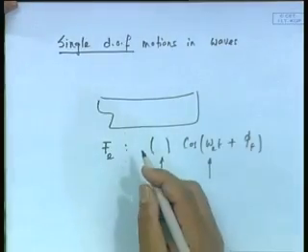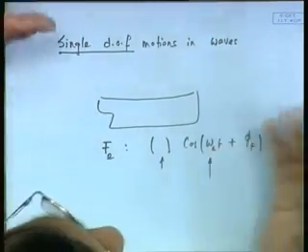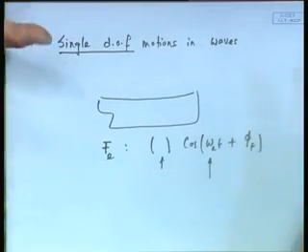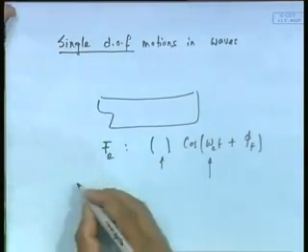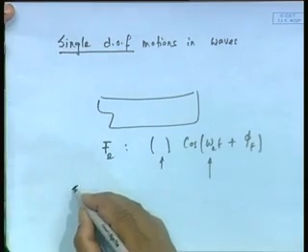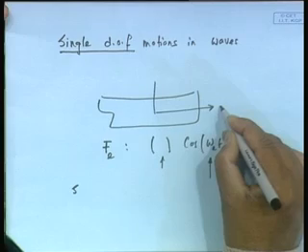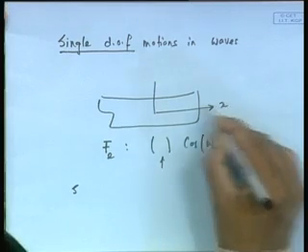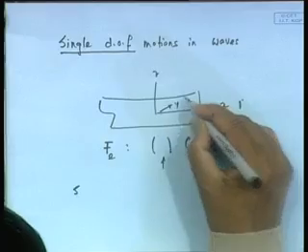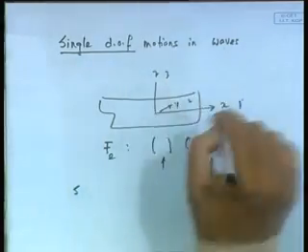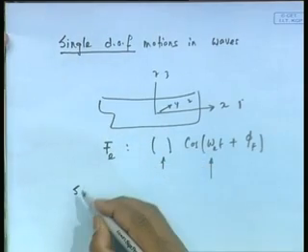So, since it is sinusoidal with one harmonic component, we would expect all the motion displacements to be also of similar form. I can call all the motions in an index form, let us say x, y, z as 1, 2, 3, and about x, y, z I am calling 4, 5, 6 to be the indexes defining those.